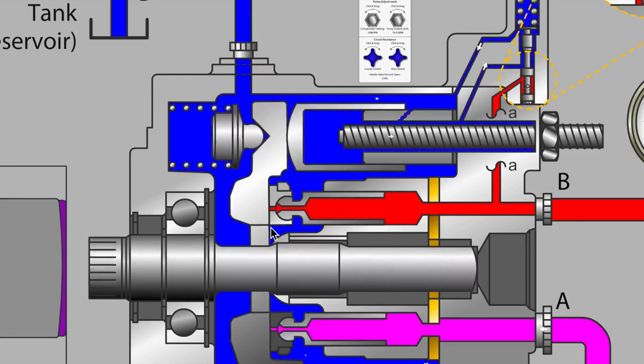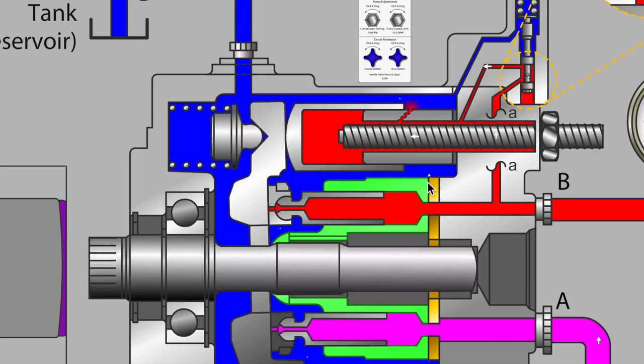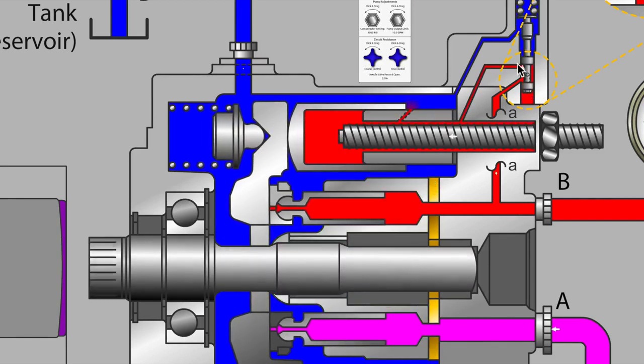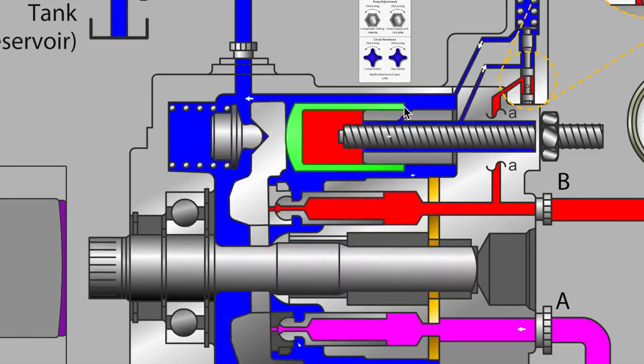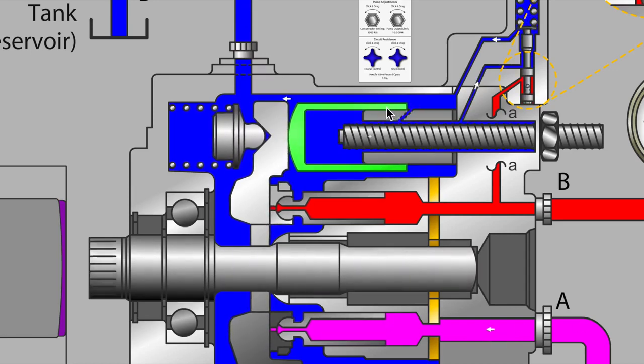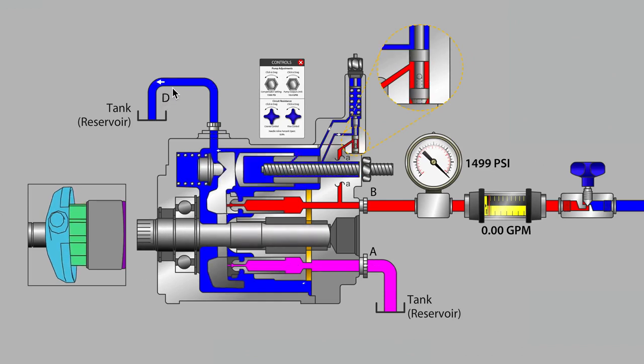So once again, the slipper pad against the swash plate, the piston ball as it is socketed into that slipper pad, that's a critical point to lubricate and a clearance. The valve plate or porting plate at the back of the pump, where the cylinder barrel meets the porting plate, and controller exhaust, and then maximum stroke for the control piston, a bleed orifice for that. So that's a bit of an introduction as to where case drain flow originates from inside the pump.